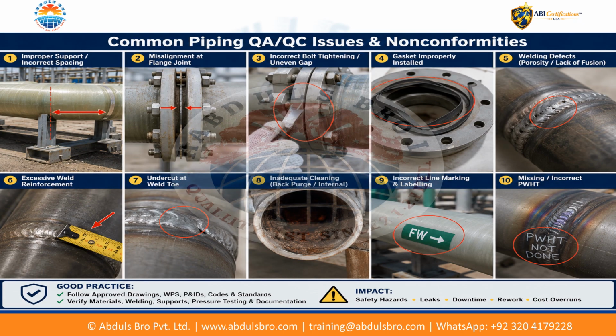Let's see what are the common piping QA/QC issues and non-conformities. Common piping quality issues include incorrect materials, loss of traceability, dimensional deviations, flange misalignments, unacceptable welds or non-metallic joints, and incorrect support installation. Gravity flow systems may also exhibit incorrect slope or invert elevation, while pressure testing may identify leakage or loss of pressure. When work fails to meet specified acceptance criteria, the condition must be identified and documented, appropriate corrective action implemented, and the affected work re-inspected and verified for conformity before final closure and acceptance.